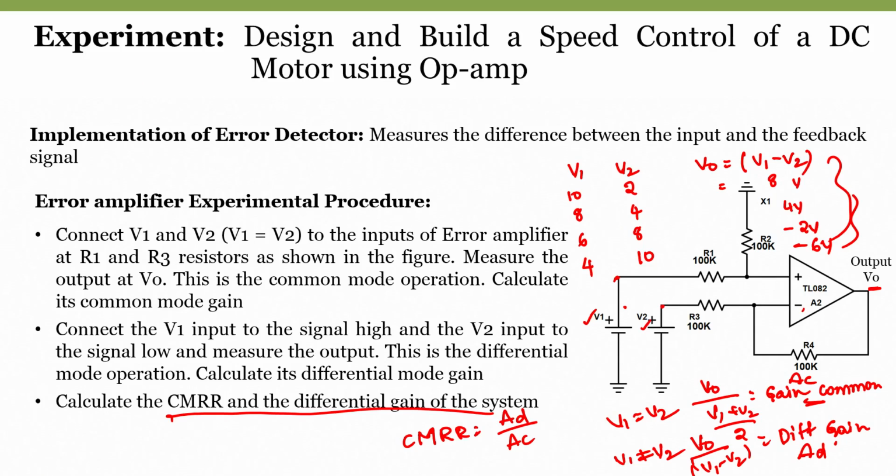Now, we will see what our actual result is. Theoretically as well as practically we got a gain of 1 and the CMRR as 58.4 dB. So, no problem with this dB for us, and we can go ahead with this differential amplifier too.